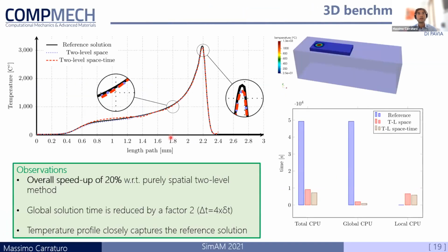So basically, we have this effect also in the other direction. And at this point, the global coarse discretization is able to capture this effect. So of course, the local domain has to be large enough to capture this, but compared to the size of even a small portion of powder bed, this is still much smaller.